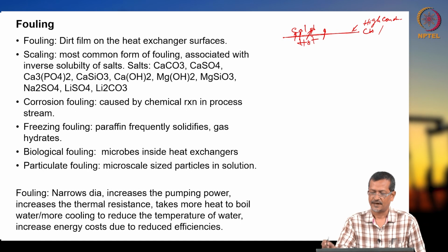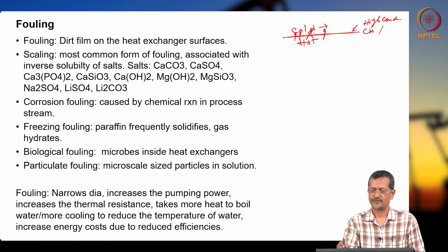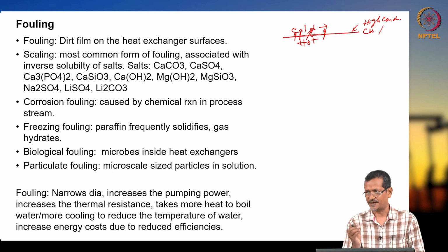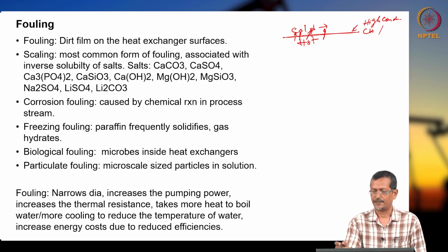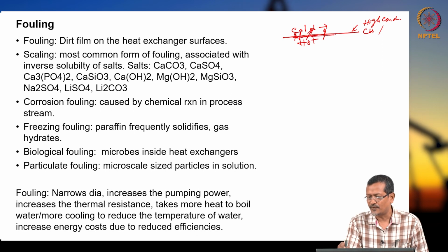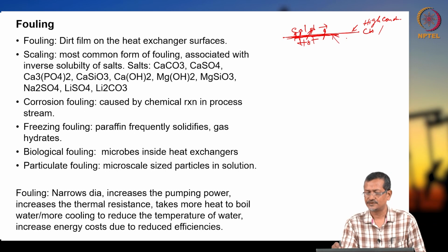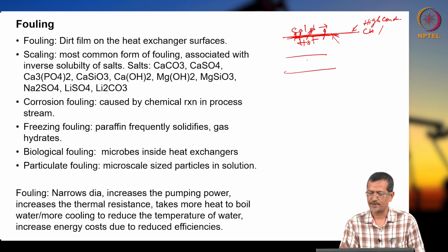Okay, high conduction should be there. And whenever heat is getting transferred and fluid is flowing, if the fluid, like water or oil or gas, has some dust particles, or some calcium salt or other salts, then what will happen? Around the solid body, those will get deposited. When those are getting deposited, your heat transfer characteristic will change. In many cases, the pipe can be blocked also.